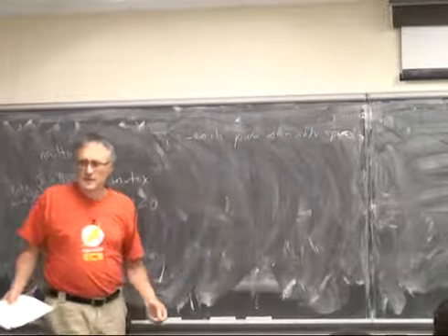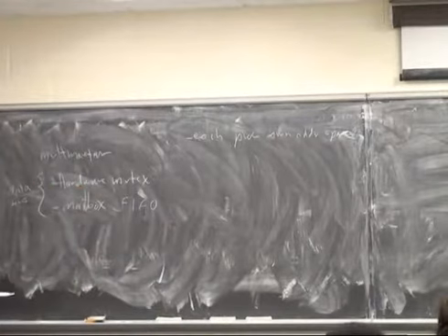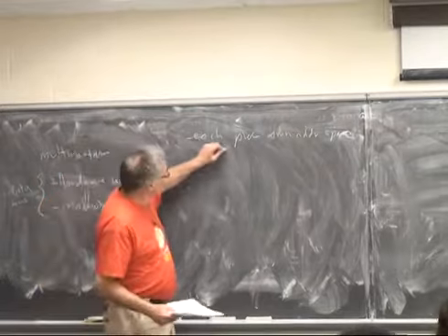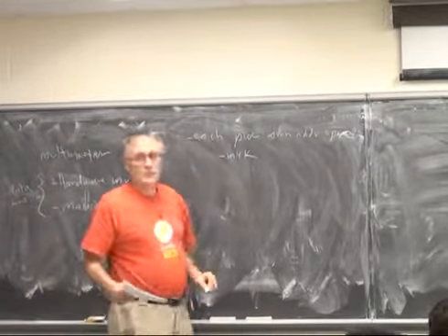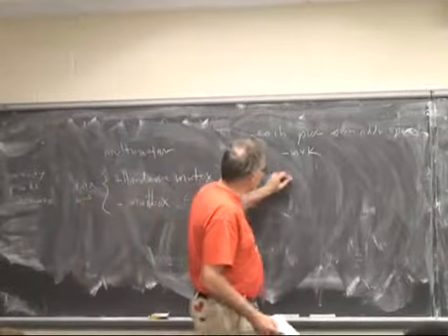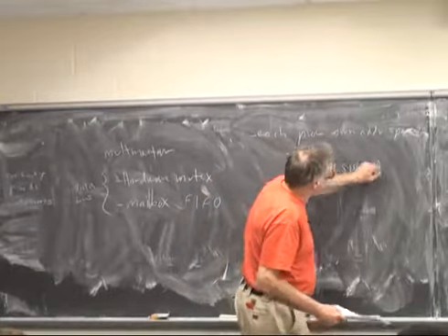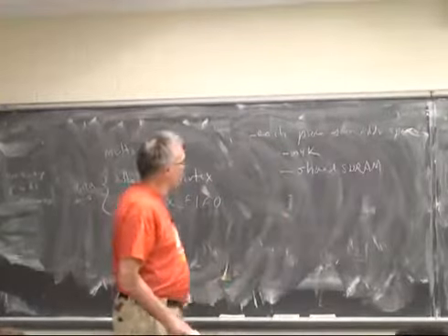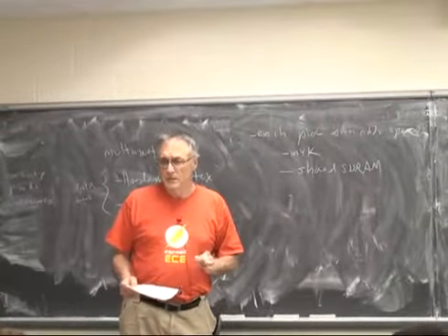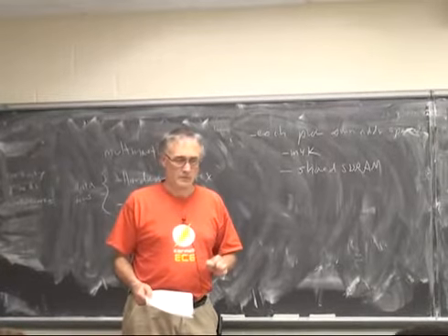You can't have CPUs executing out of the same code. And, well, maybe you could. And this can be disjoint, so it could be M4K blocks, could be completely disjoint. Or it can be shared SD-RAM. And if it is shared SD-RAM, then the reset vector for each processor determines the lowest address that that processor has access to.